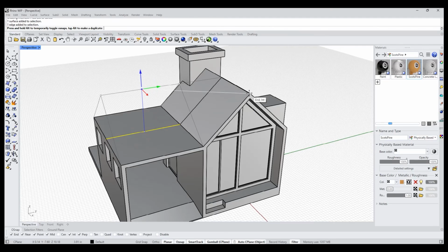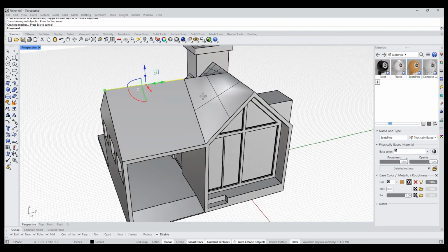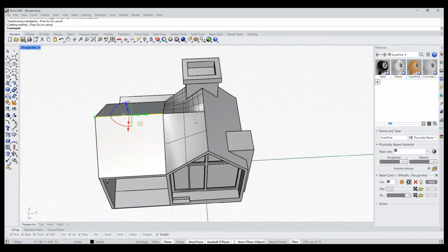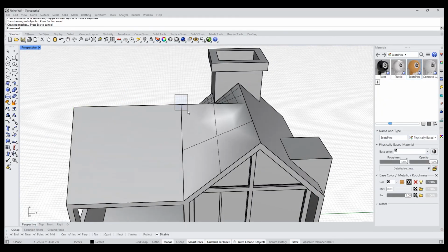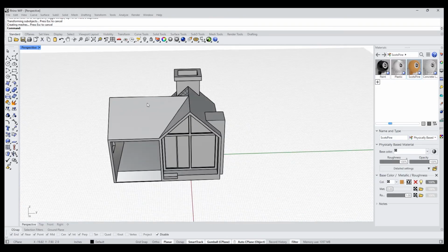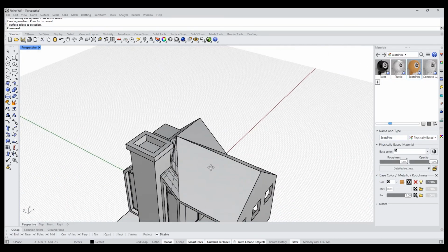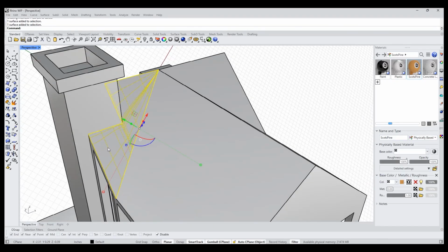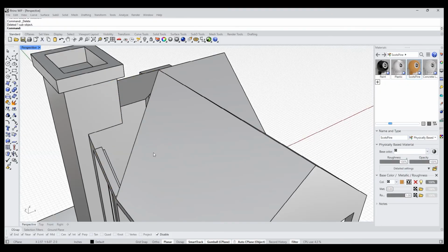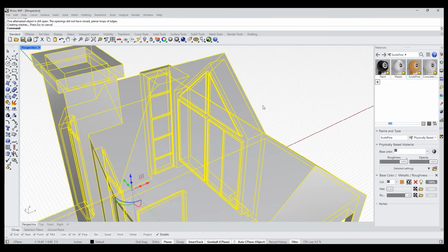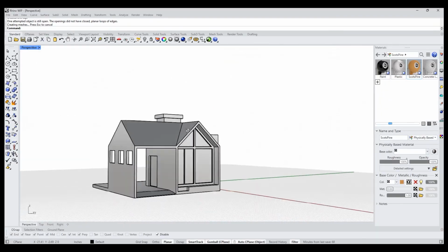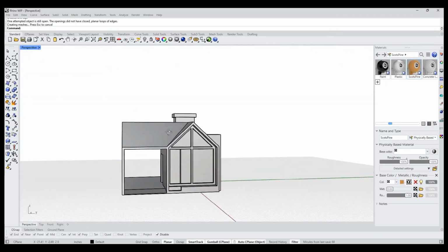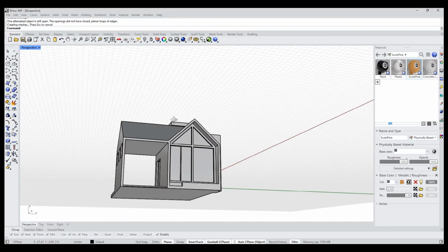But what we're going to run into is a problem where this stuff back here starts to twist. And so the fix for that is we drag this point over and we go like that. And that fixed this one, but it left us with a mess back here. I'm just going to delete it and then I'm going to run the cap command. And it's going to replace that tortured surface with a nice, clean, easy one. And so now we just went from one style to a different style.